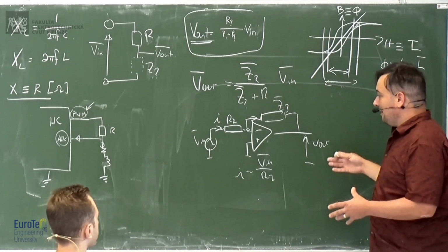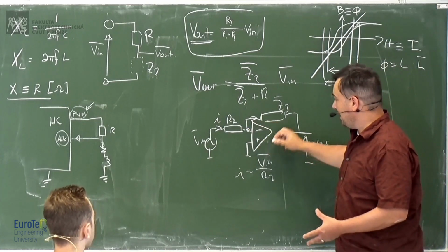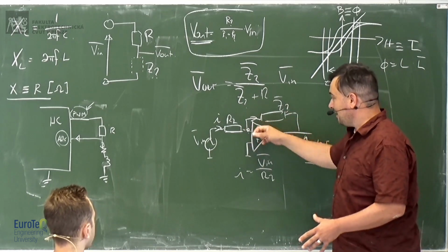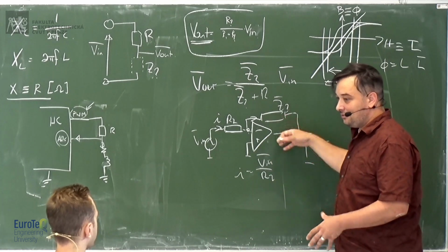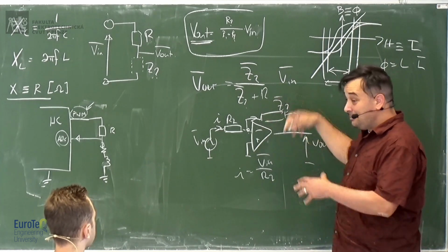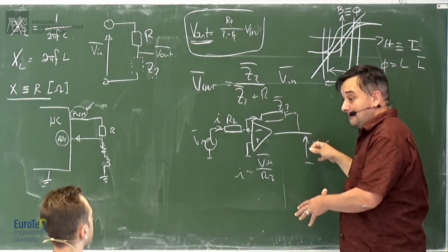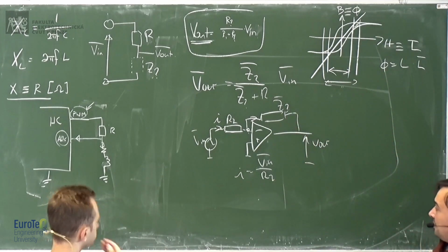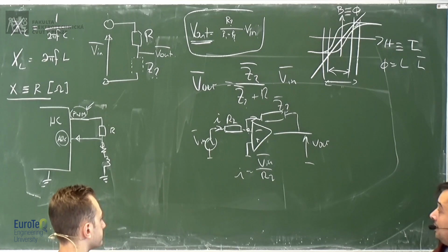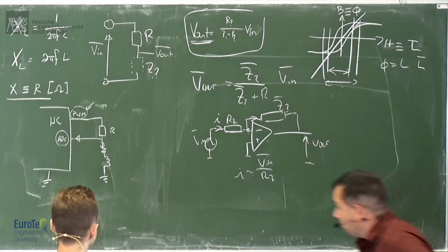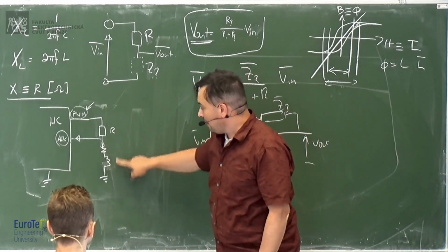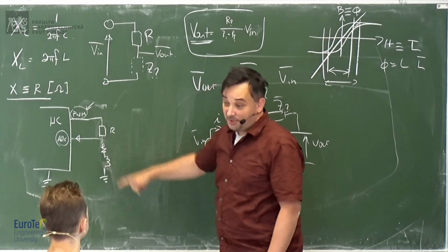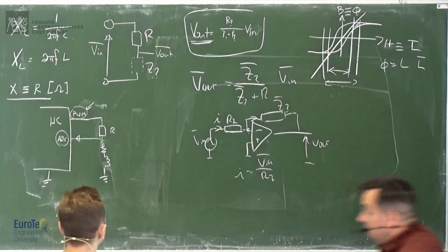So always, as much as possible, when you're talking about sensors, and the output will depend on the current that you inject, just try to keep the test current that you feed to the impedance, to the resistance, to whatever you want to feed, independent of what you want to measure. So this is something that I would always recommend. And unfortunately, this is not true, unless, as usual, you have this resistance much bigger than this one, so that the current will depend mostly on the resistance, but then the voltage will be small. Okay? You need a precise ADC.